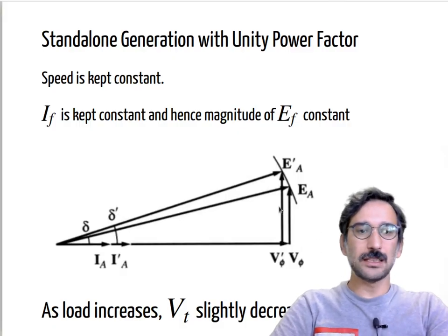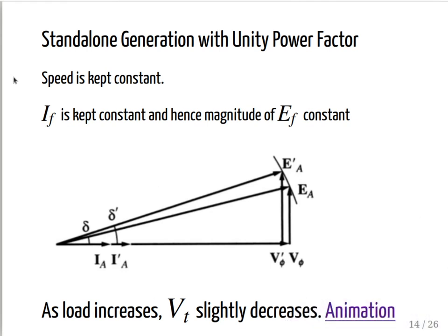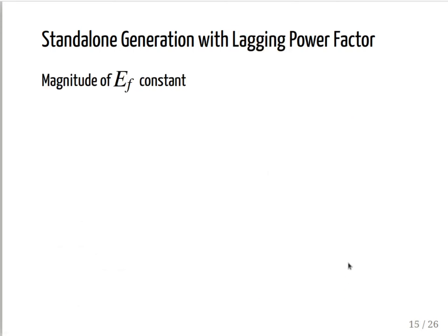and then we have the terminal voltage with respect to the magnitudes of these two parameters. So if you think from that point, it should be clear that as I increase the load, the magnitude of terminal voltage drops. It is like a transformer, you can think like that. It is a transformer working at unity power factor, and as the load increases, the output voltage actually reduces, and you can see that. So there is a voltage regulation problem, and you can see more animations in that link.